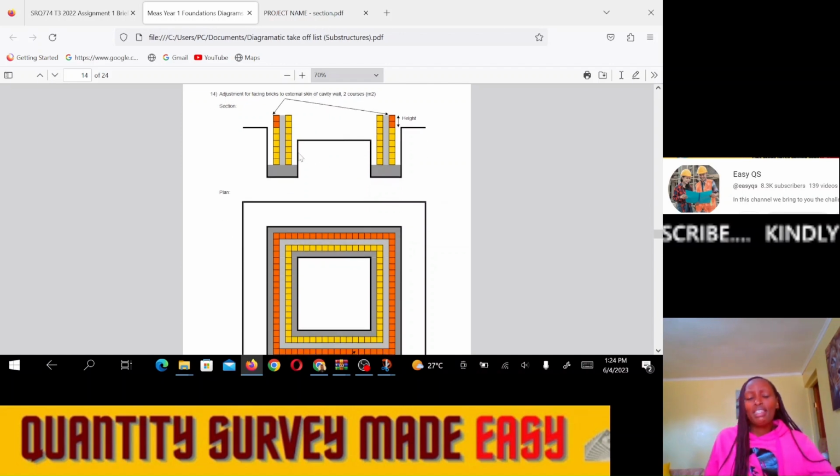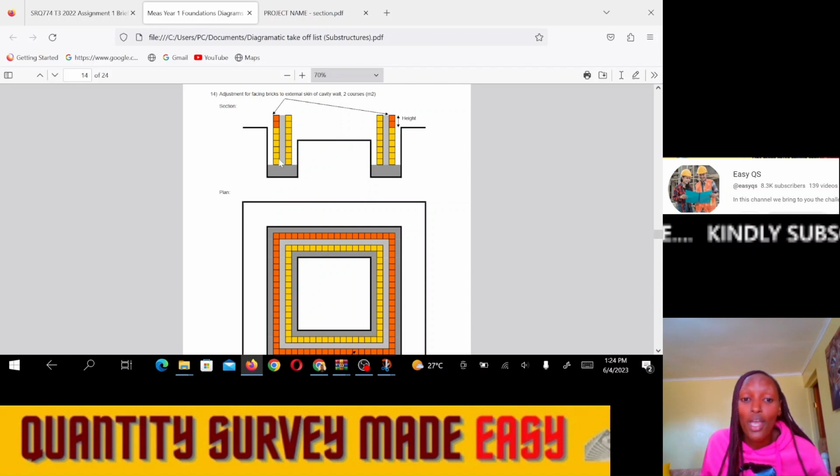After we have constructed the bricks, there are those bricks that are usually thin. You see, this is the substructure works, but the floor of the house is always above the ground level. So there are those bricks that you shall be seeing from outside, but they are on the substructure. These bricks are supposed to be a bit beautiful. That is what we call facing bricks. They are made to be aesthetically nice.